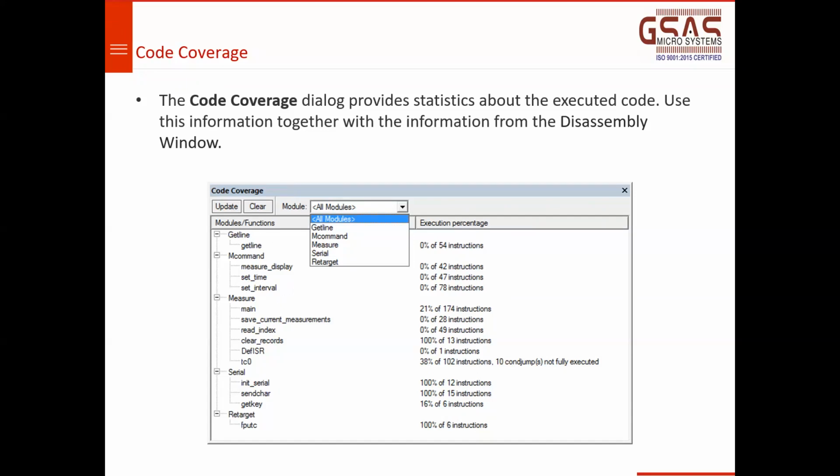But this plays a critical role if you're getting your product certified for functional safety applications, or if your product is going to industrial automation, automotive, railway or medical. Code coverage gives you information on what paths or C statements the processor has executed. And the code coverage should be 100% to get your product certified. This is code coverage along with the trace information.